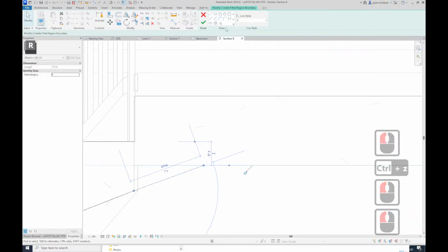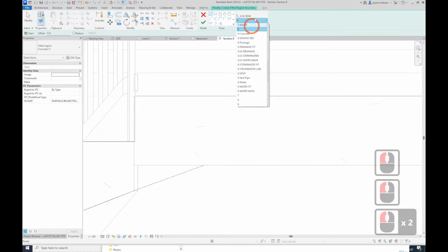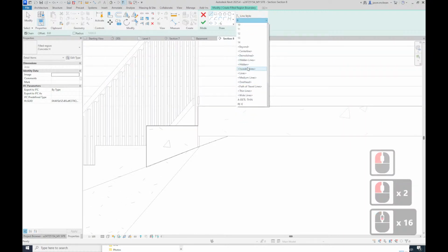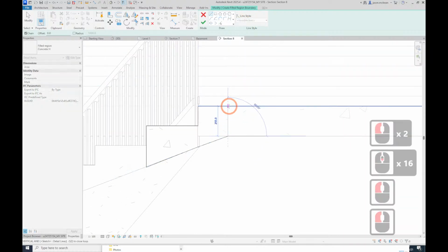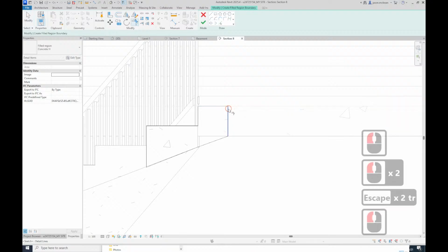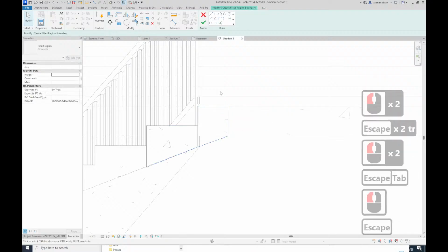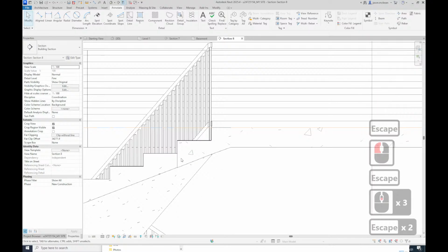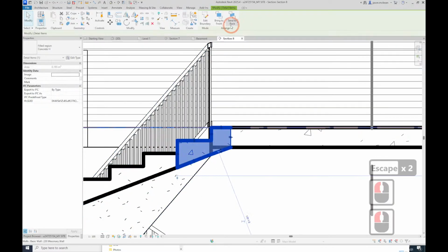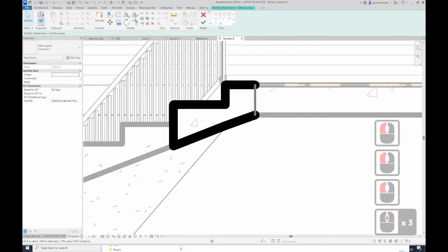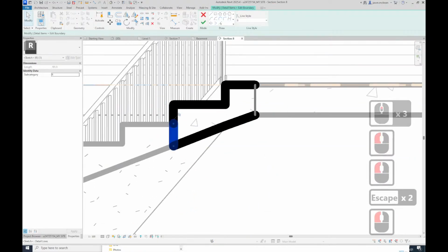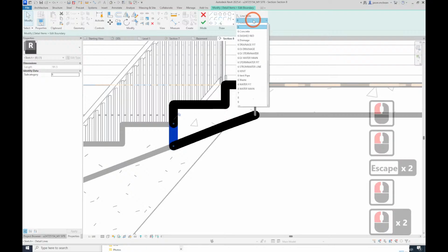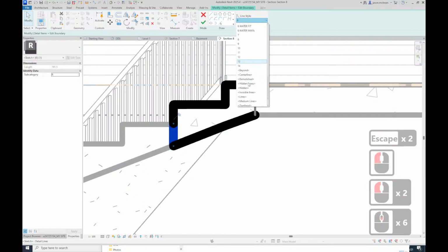Where this connects, I wing it. I use the invisible line now because it's never visible. And this has to be a closed set of line work, like that. Finish command. See what it does? It just connects it. And that one would also be an invisible line. So you're going to go here again, hit sketch, you're getting it. Split line, on that line there, guess what? That one invisible line. So it just looks less weird. Revit never joins them.